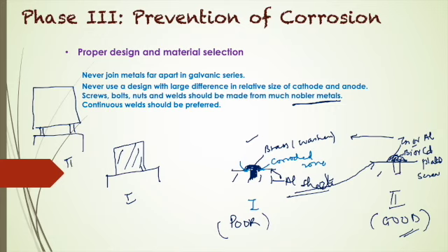So option number two actually is a better choice. This is a much better option as compared to option number one, which is actually a poor option. Why? Because it is easier to clean this part as compared to this part, and the space between my instrument or my machine and the floor, that space is sufficient enough for dust and dirt to deposit.